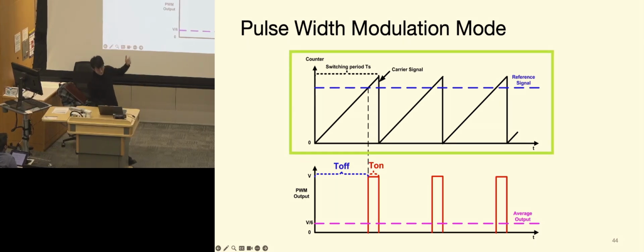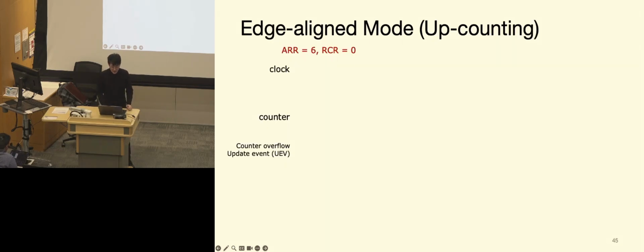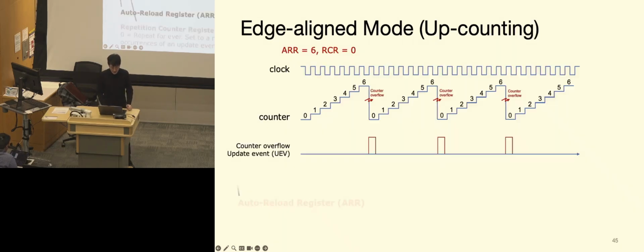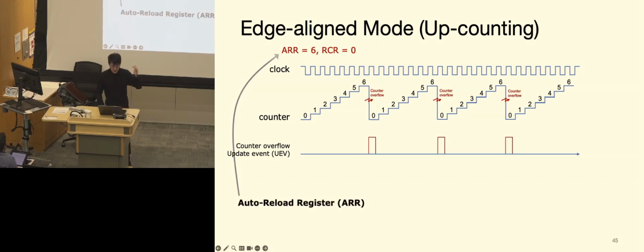First, we set the timer, or the counter in this case, the upper part. We can configure the counter to repeatedly count up. For example, if we give it a number of 6, it counts from 0 to 6, 7 steps, and then keeps doing that until you kill the system.